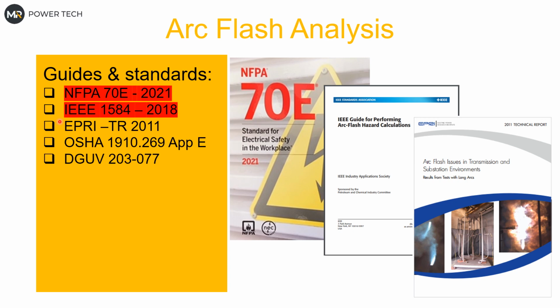So from transmission level we can go down, but that's in EPRI and OSHA, and ARCPRO is sometimes used. So that's if we go from high voltage, medium voltage system down to 15 kV. From 15 kV down to low voltage system, we use IEEE 1584. And low voltage system means, in a practical way, most of the time we do it down to 63 amp protection level. But in IEEE it is specified as 2000 amp short circuit level, or at 208 volts, so in our case